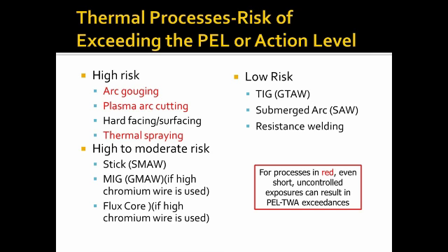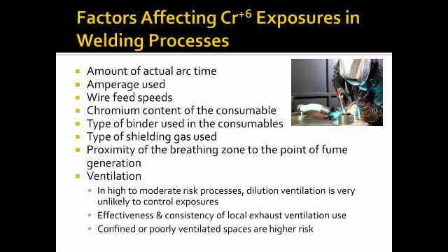The binders that are used in some consumables, particularly stick welding operations, you tend to find hex chrome levels high in those because the calcium and potassium and other binders that are used in there actually combine with the chromium and stabilize it, and that hex chrome which is created tends to hang around a lot longer, so sometimes you'll find higher exposures from that. Certainly ventilation, which Bob is going to talk about in the next session, will be a big factor in that, and I'm not going to dwell on that a lot more other than to say it certainly is a factor.